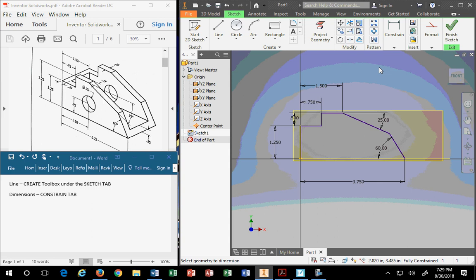Now, does SolidWorks or Inventor, in this case Inventor, warn you when it drops dimensions that it actually can impact your tolerances? No! You need to know that. That's why I'm making it a conversation piece right now. When we made this object, just like this one, we made it expediently, but not correctly. It's expedient, but now we have to go back and correct the dimensions to be exactly the way the customer showed it on their drawing. This is their drawing. Got it?